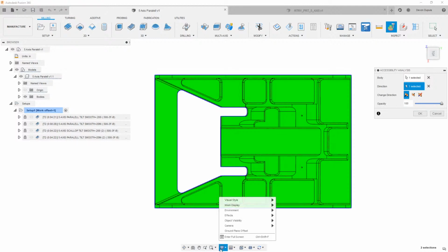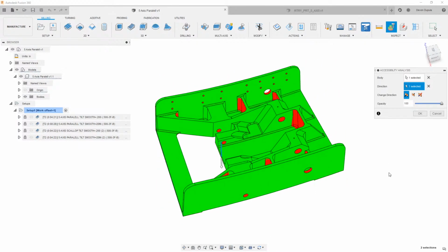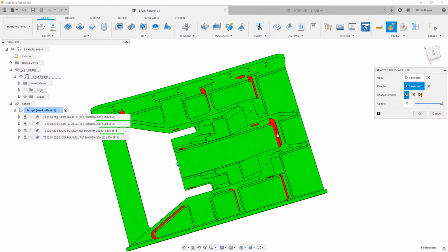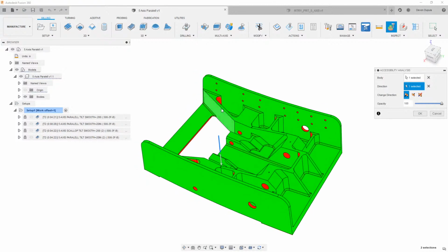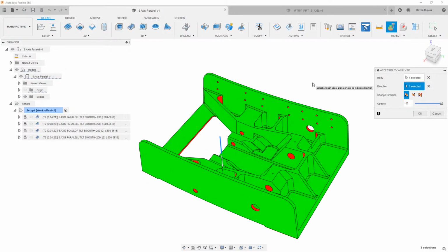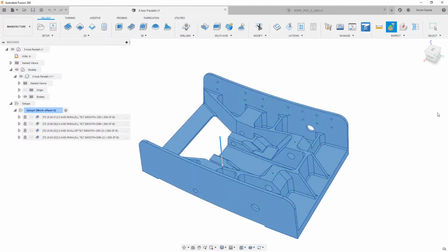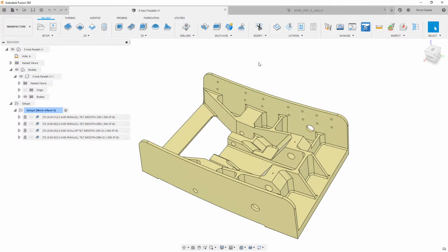I also happen to have perspective with Ortho Faces. This is kind of my favorite view. I like orthographic when I'm looking at a normal two view, but not really all the time. So this is a great, kind of in between for those views. You can see when I rotate this, we have all these undercut areas on here, and this just helps me visualize what areas I'd be able to machine and what I might need to set up, multi-axis 3+2 or additional setups if I just have a 3-axis. So I'm going to close this out for now, and we'll come back to this part later.